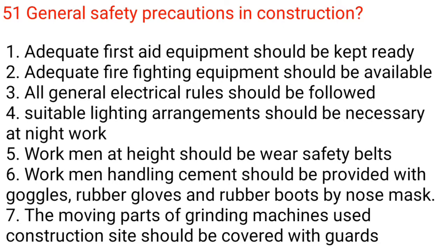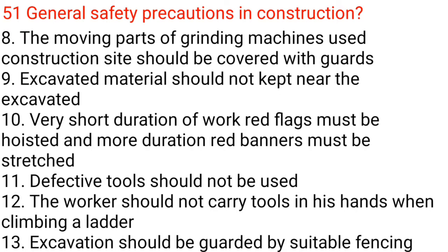5. Workmen at height should wear safety belts. 6. Workmen handling cement should be provided with goggles, rubber gloves, rubber boots and nose mask. 7. The moving parts of grinding machines used at construction sites should be covered with guards.